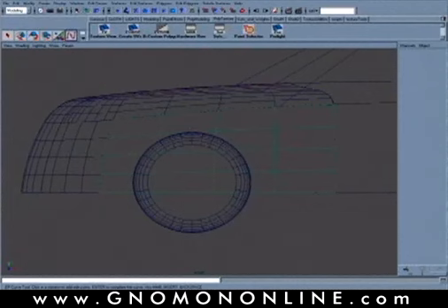So with the edit point tool, I'm going to snap this so that our first point represents somewhere down here before we leave that other surface where we want to begin translating, and then put another edit point somewhere towards the top. It can almost hit the edge of that other surface there, and then come back down on the bottom side again. So we're snapping it back down onto the edge of that other surface.